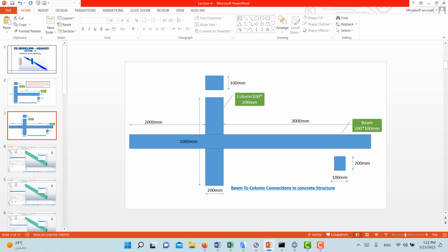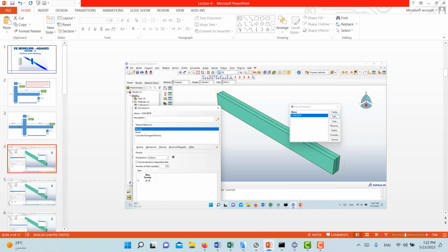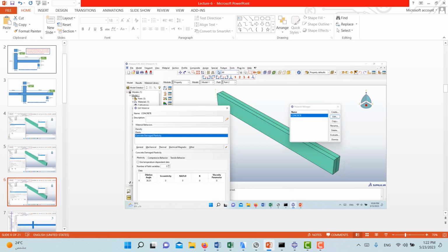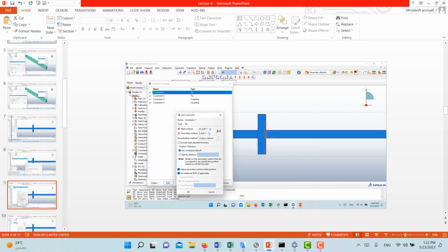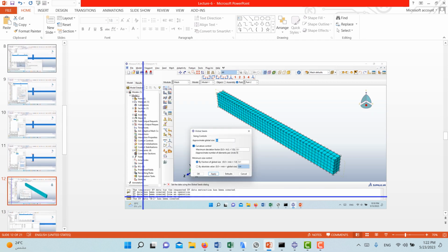So after drawing the beams and setting the properties for the components, this is the properties which is very important. It could be density, elasticity, etc. Then determine the type of analysis and choose the appropriate meshing. Meshing is a very important thing in my point of view, which is related to the shape of the meshing, not just the value or the square.